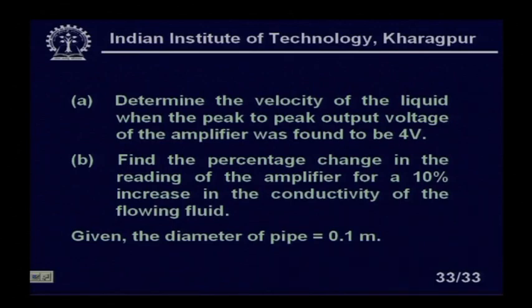So, this problem is very straightforward, but I am giving the equations, then I will give you the answer. I will not solve the full problem. So, I can take a blank page. It will look like that, E is equal to here 2 volt. Now, the output voltage will be given by E minus I R internal equal to I into R amplifier, right.